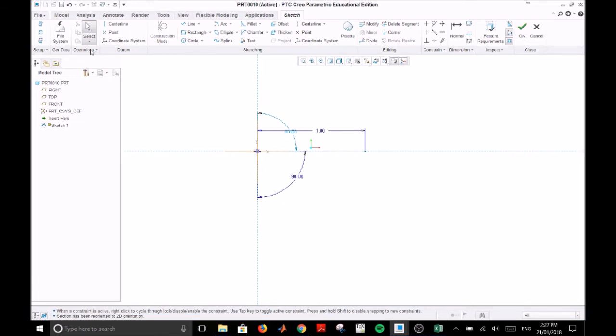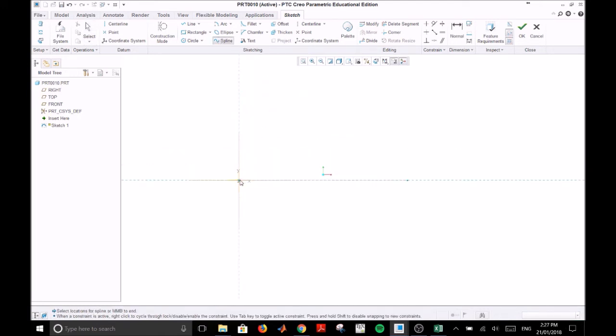Okay. I'll then sketch a spline. This is for the top surface of the airfoil. So we'll start at 0, 0, 0. I'll just put an arbitrary point, and we will end at 1, 0, 0. So that defines our top surface, and I'll do the same for the bottom surface. So it's not a very good looking airfoil, but that's okay. This spline geometry will be modified to the points that we've input from Notepad.